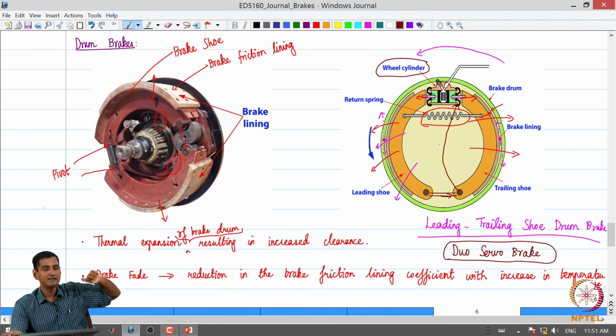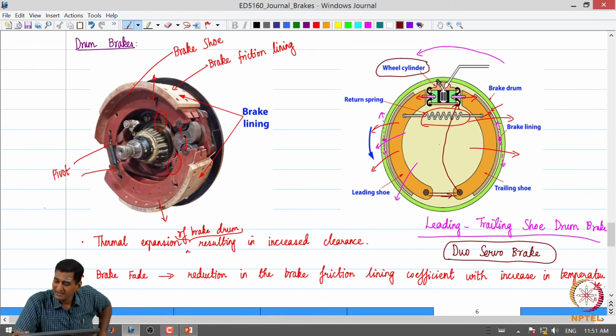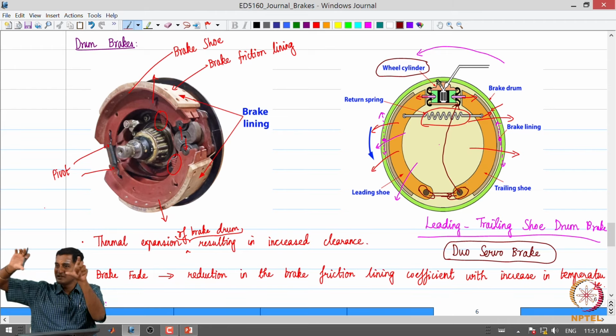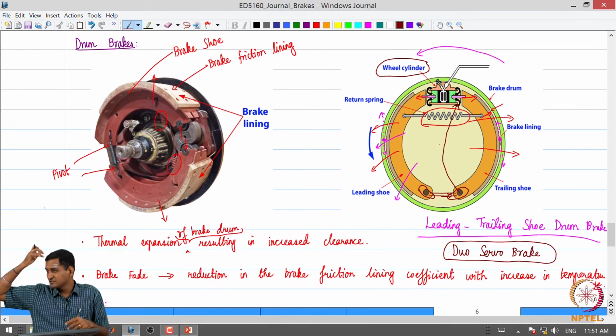That is the concept behind self adjustment. Due to that, these pivots are no longer rigidly fixed, but, exaggerating to convey the concept, they can be moved in some slots, because we want to push the brake pads closer to the drum if the brake wear is more.